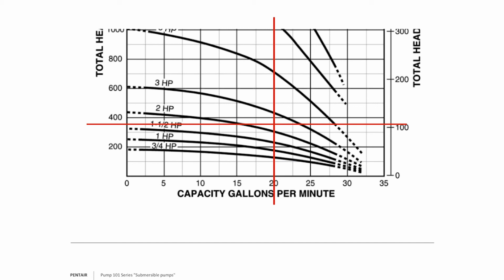Would that possibly damage something in the home? Well, yes. But remember, in a residential application, we're pumping from the well directly into a pressure tank. That's why the pressure tank is critical. That pressure tank can absorb the extra pressure and flow to balance it out in the home so the home does not see that extra flow or that extra PSI. Okay? So maintaining the tank is critical.